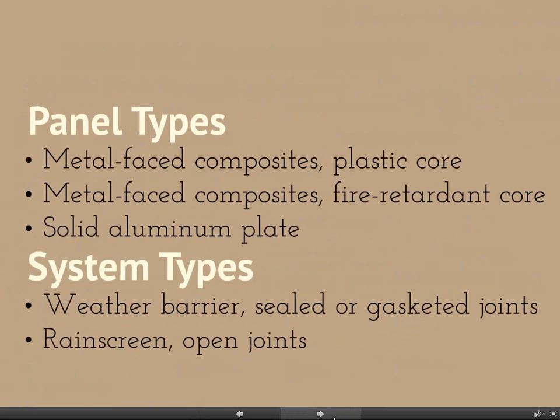Yes, and Brian Payne has also pointed out that the NFPA 285 is required for ACM installations within 5 feet of a property line. So there are other considerations, but those are the primary ones.